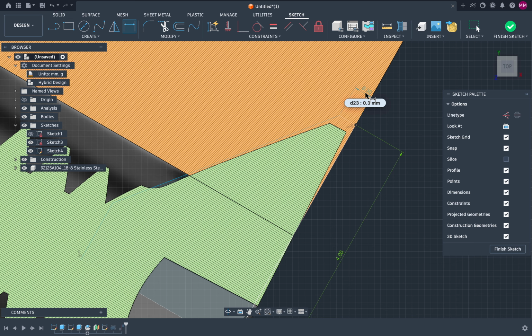Also, in our case, because we are not only engineering it in this imaginary world, we also want it to be working fine in the physical world, we need to do some tolerances, right? And give it some space, since 3D printers are not perfect and there is a giant margin of error. So let's go ahead and actually change it to 0.4. Great.